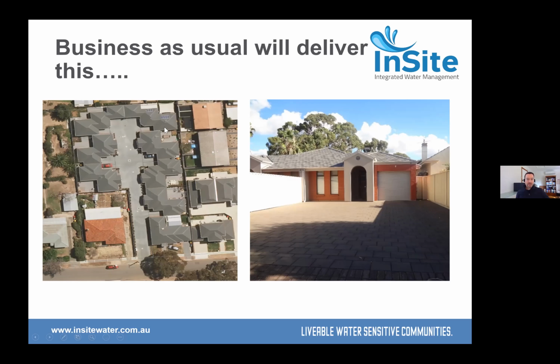If you can imagine the difference between a big pervious backyard and a redevelopment where rainfall hits these roofs and paved areas and runs straight into council drains, you can see that a lot more rainfall runs off when a site is redeveloped, both in volume and flow rate and in terms of the pollutants running off the site as well. And this puts huge pressure on existing drainage systems and on council assets.